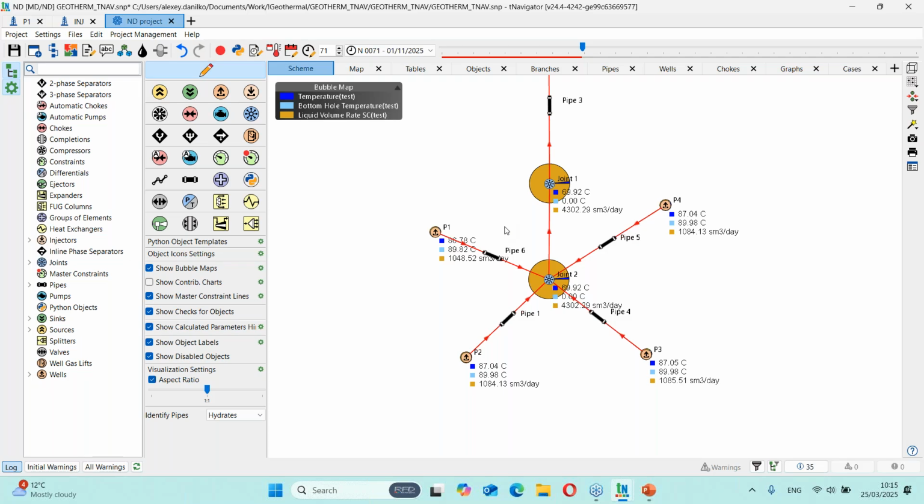So you can select the thermal conductivity of the layers, assign the thickness of each layer, and select the number of layers. In that case, the heat transfer coefficient is not taken into account. We calculate the temperature losses based on the pipeline description and the thermal conductivity of the layers.